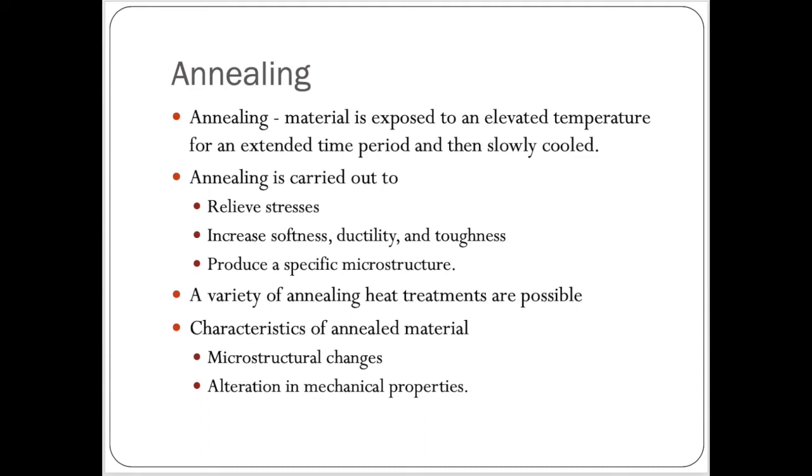Ordinarily, annealing is carried out to relieve stresses, increase softness, that is ductility, and toughness, and also it is used for producing a specific microstructure. A variety of annealing heat treatments are possible. They are characterized by the changes that are induced, which many times are microstructural and are responsible for the alteration of mechanical properties.